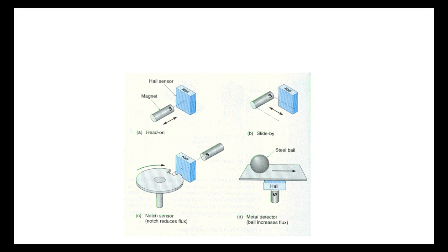As soon as I say solid state, it would mean I go out there and disconnect my battery and turn your radio on. What's your radio going to do? So it's electronic. It's solid state. Before it does anything, it's got to be what? Powered. So it's at least a 3. So we can get 3-wire sensors and 4-wire sensors. So these we don't have a contact. We got a device that simulates a contact. We call them bipolar transistors. We saturate them and then they conduct current.